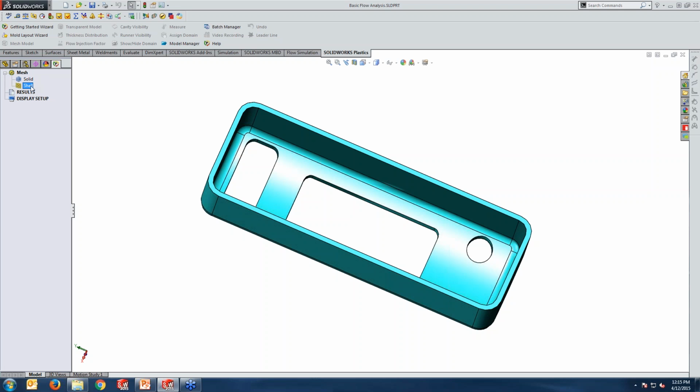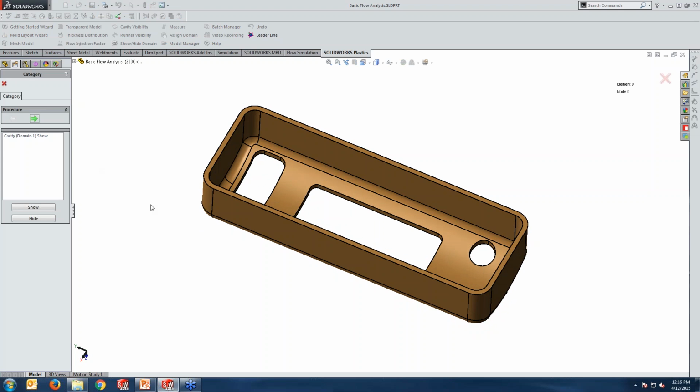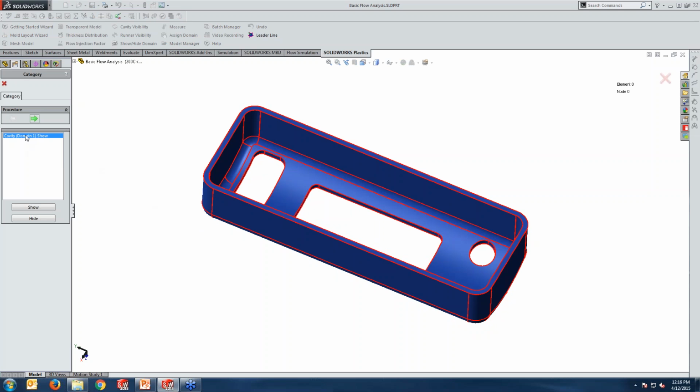Okay? All right, so in order to create the mesh, as a first step, you have to right click. You have the option to go automatic meshing or manual. Let's click on manual this time and have a look at what is happening. The first thing is the software is asking where I have to mesh. There is one cavity active and you can look at it and basically say this is where I want to mesh. Click next.